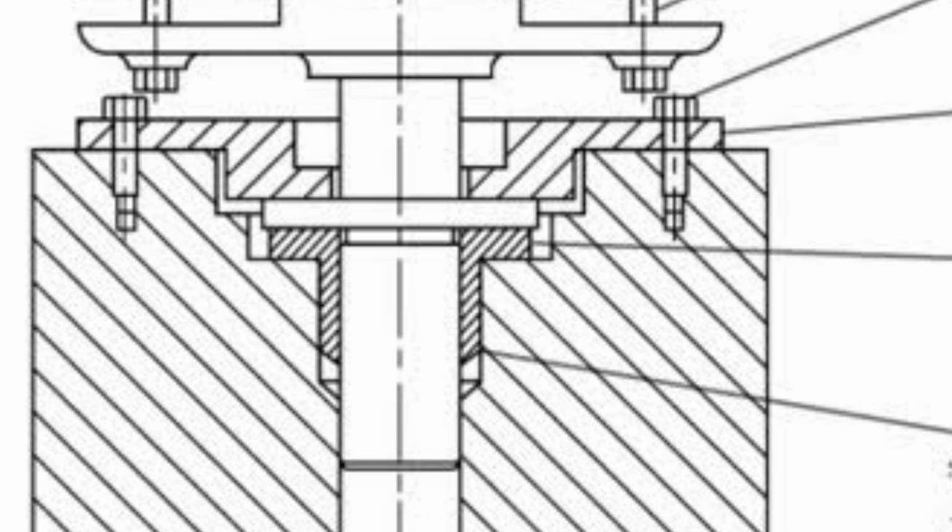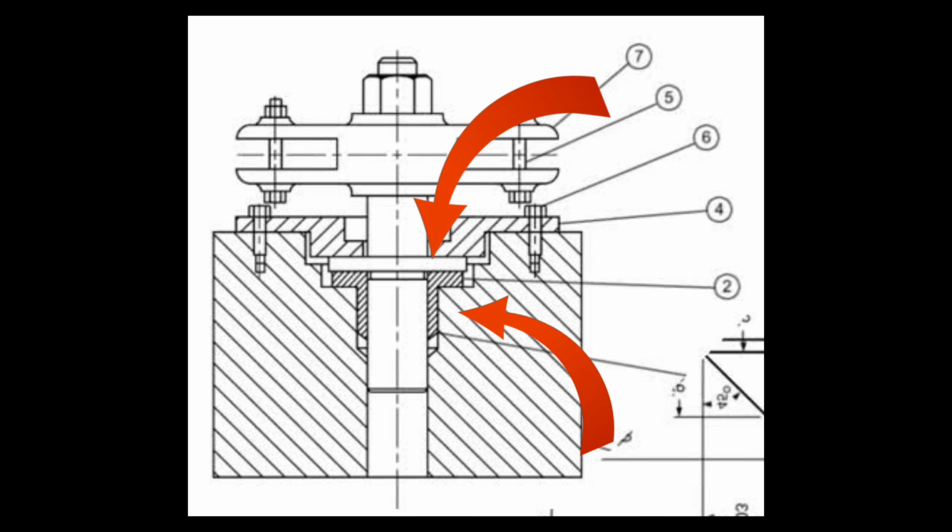Don't care what anybody else has said to you. 45 degrees is the standard, and that's as much as it goes. You cannot do it any old angle you want. It needs to be 45 degrees. 45 degrees is the standard drawing convention for cross hatching. No other angle is allowed. The only thing you can change is the pitch, which is the gap between the lines, to indicate separate parts, as seen in this image here.